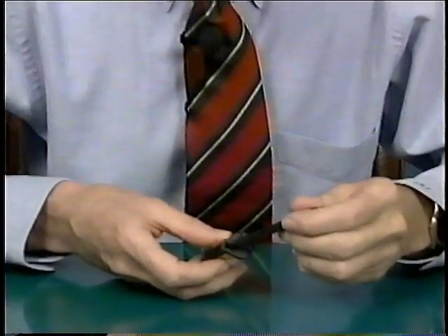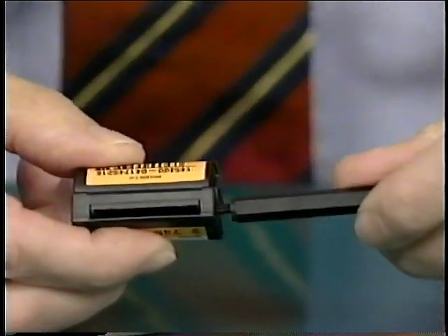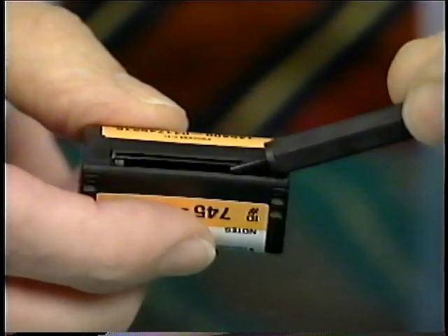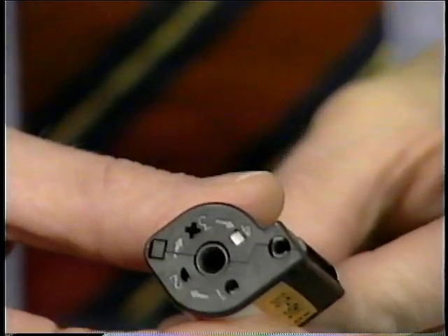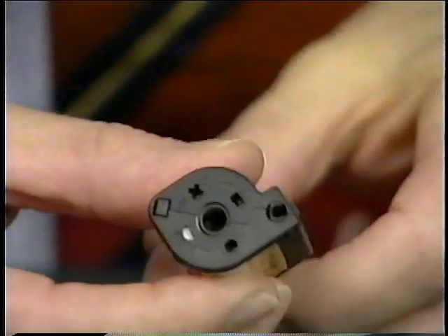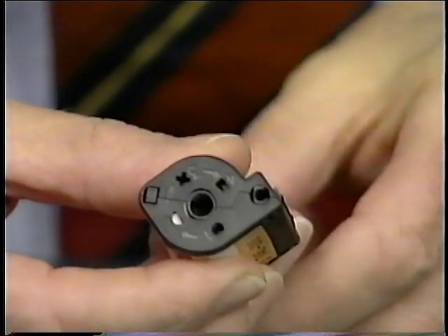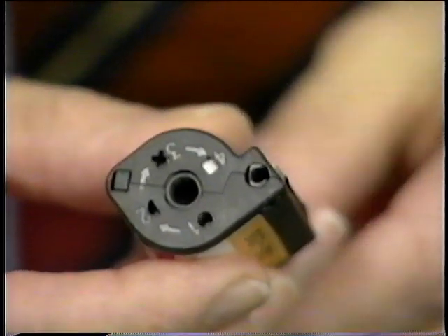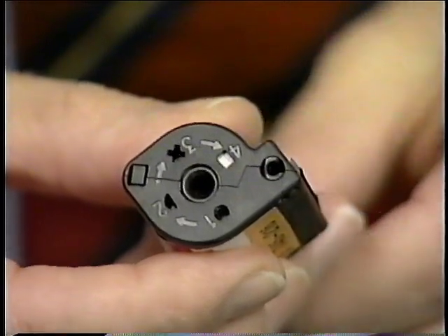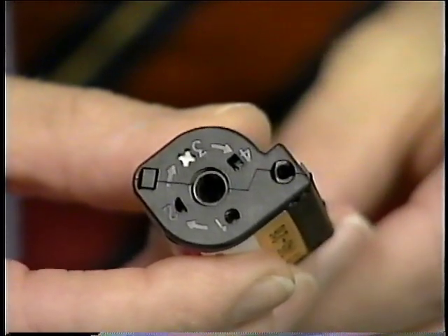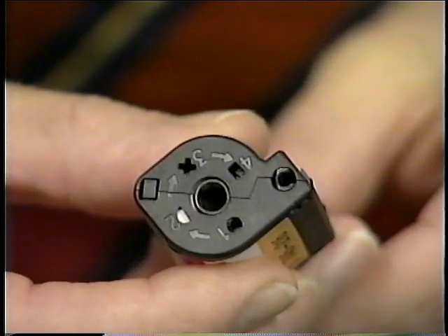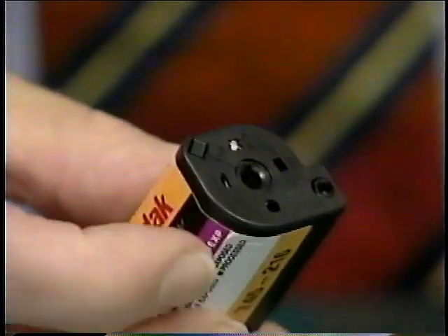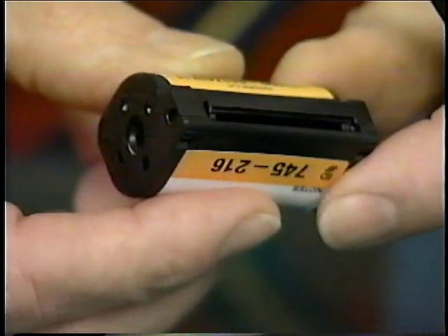When a cassette is first placed inside of an APS camera, the first thing the camera does is open the light-tight door. In other words, it will turn this and open the light-tight cover, and that will, as we said, release the spool to be turned. It will then turn in the rewind direction, and you notice as I do this, we can change the position of the status icon. And what happens is when the film is rewound after exposure back into the cassette, the camera continues to run until it positions this icon, for example, for exposed or perhaps for partially exposed film. Then the camera stops, closes the door, and it's locked into that position.